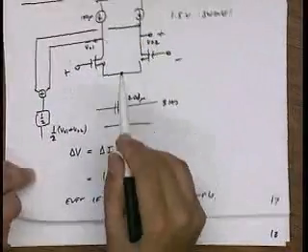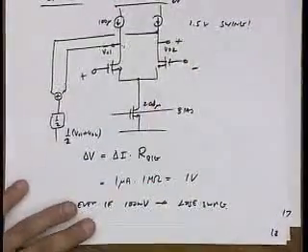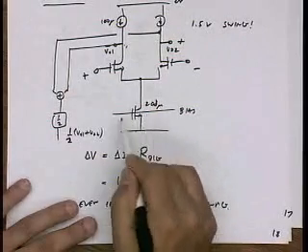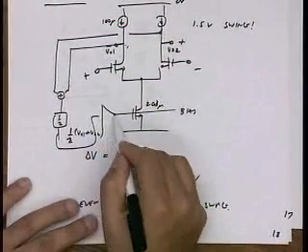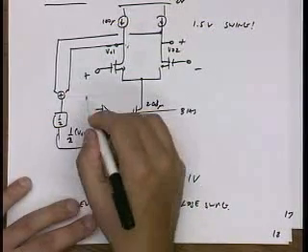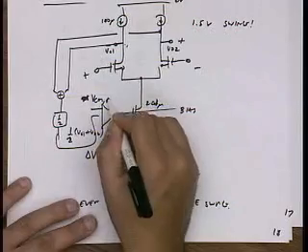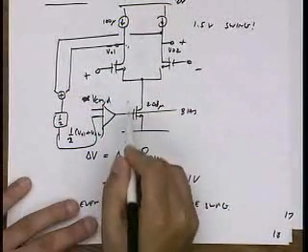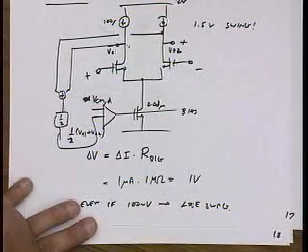what's a good way to change the common mode of this circuit, right? What's a good knob to turn on this circuit? Oh, this is a particularly good knob, right? So if I now take this, compare it with the desired, let's just say V common mode D for desired, and then adjust this voltage to stabilize the common mode, I'm in business, right?